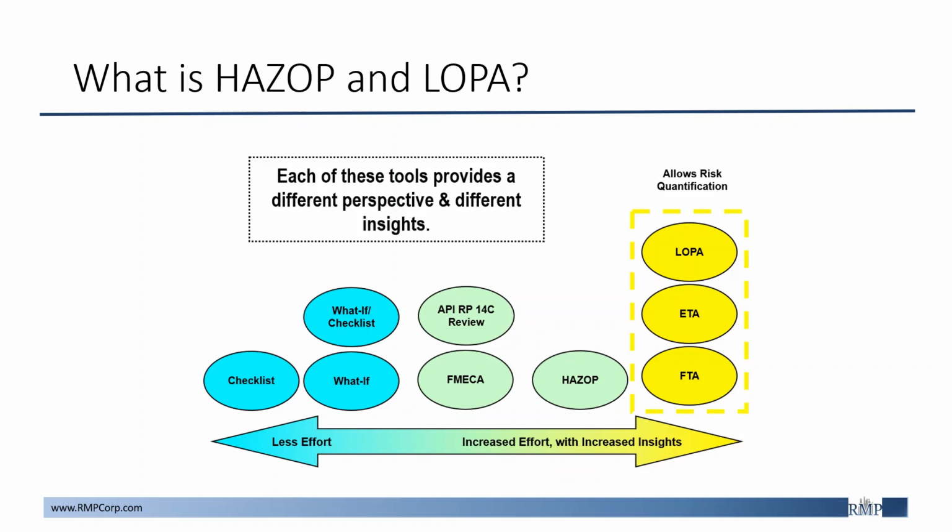For potential hazards identified in a HAZOP that need further investigation, the layer of protection analysis, aka LOPA, is included to identify appropriate reliability targets for key safety features. Although the process of performing this type of study has not changed significantly over the years, it is important to note that the expectation for quality has increased, and thus it is important to get the most out of your HAZOP.